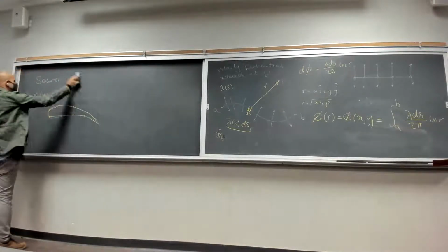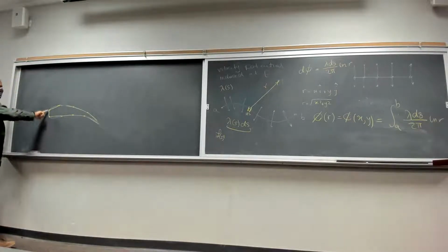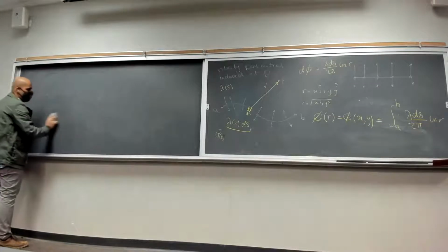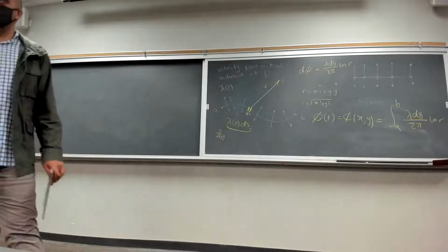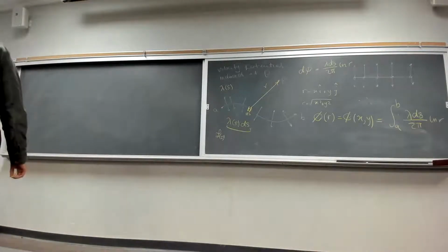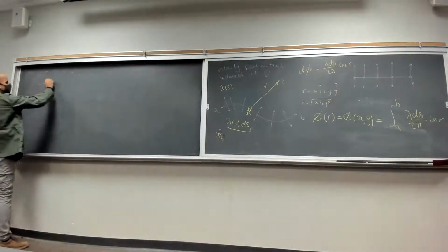As long as you can define a source sheet that can resemble the shape of this airfoil, you should be able to calculate that integral, right? But the idea here is that we cannot find this type of source sheet, right? We want to make it simpler, right? So we are going to divide, I'm going to draw this again here.